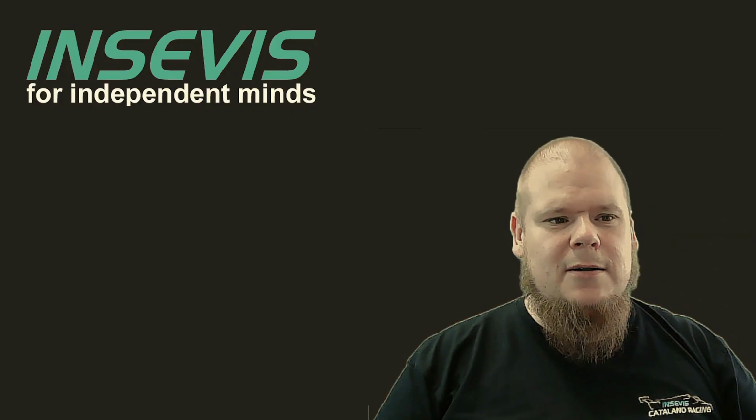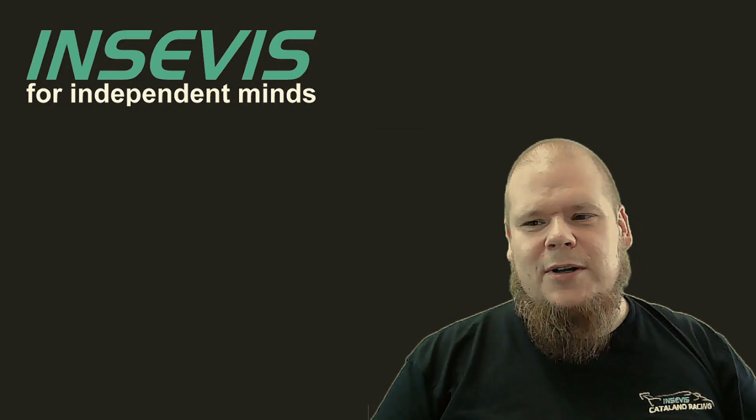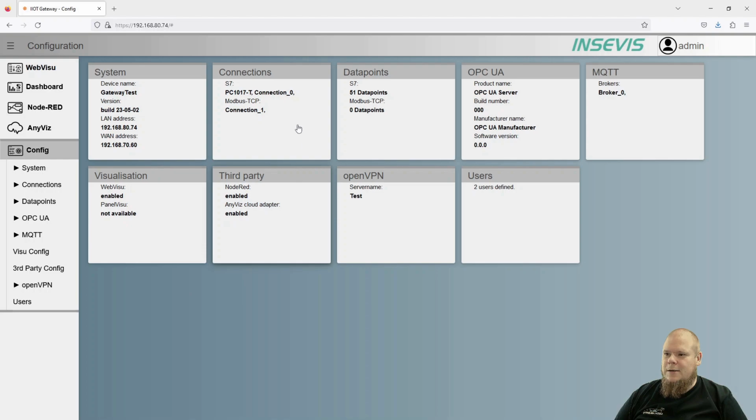My name is Fabian, and today I will show you how to create connections and data points in your IIoT devices. In the main menu, we find the two tabs, Connections and Data Points. Under Connections, all connections, both via S7 and via Modbus TCP, are created, and under Data Points, the corresponding data points.